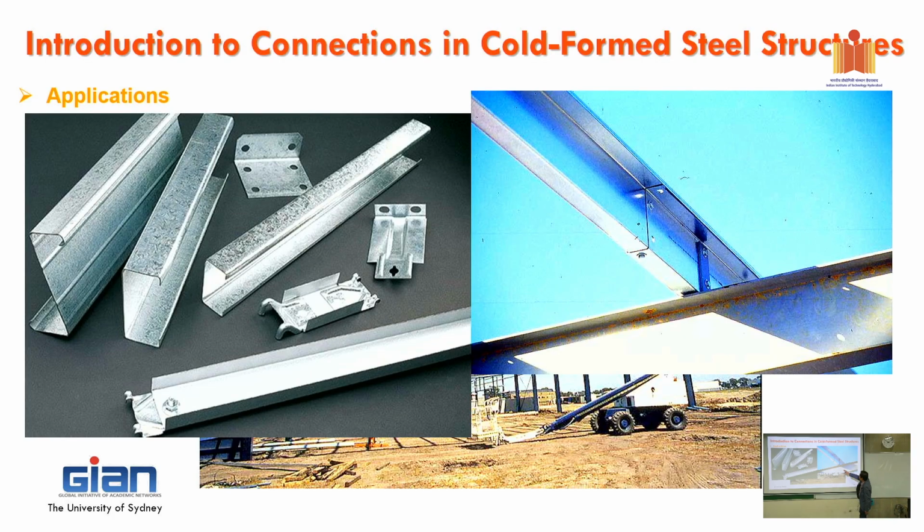And then we bolted straight away to one cleat with two bolts. And one cleat here will be welded to the top flange of the girder. So in order to do that, you can see there's a little bit of a gap here, so we can avoid the localized loading that we know, right? But DSM can allow you to design for that one. So if you need to design that, you can actually check it.